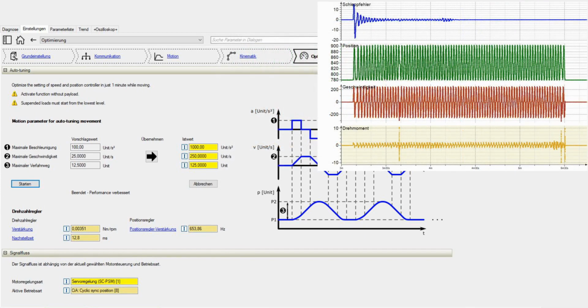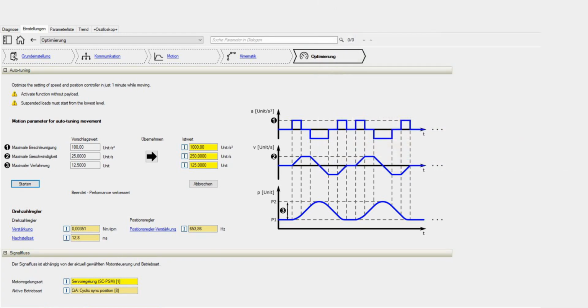A look at the trace shows that once again a significant reduction in the tracking error was achieved very quickly. This time, a maximum tracking error of 0.005 is achieved as the best value. Compared to the last design, the value was thus halved. Moments of instability during optimization are again very clearly visible in the torque. In principle, this concludes the presentation of the auto-tuner.